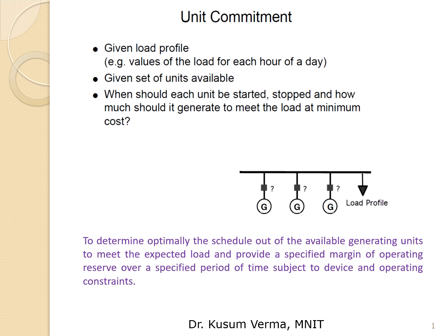Now, what does optimal unit commitment mean? It is not economical to run all the units all the time. So, to determine which of the units of the plant will operate for a particular load is the problem of unit commitment. And this problem is important for thermal plants because for other types of generating plants such as hydro, their operating cost and their startup times are negligible. So, their on-off status is not important.